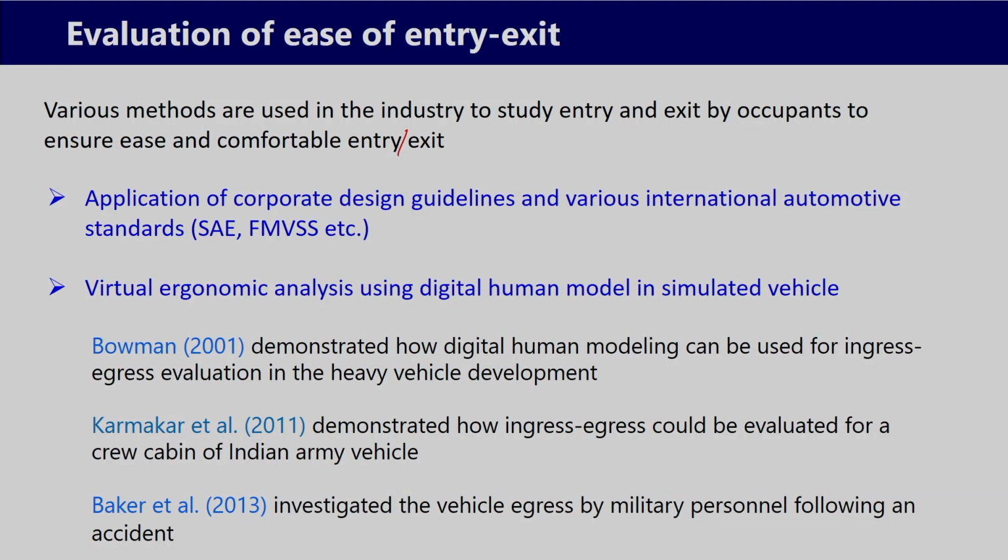In this research paper, he showed that for a heavy vehicle like a truck, while the driver is climbing up or getting down, 3 points of contact are to be maintained, either 2 hands 1 foot or 2 feet and 1 hand. These 3 contact points should always be maintained to maintain the balance of the driver while climbing over the stairs or going inside the vehicle.